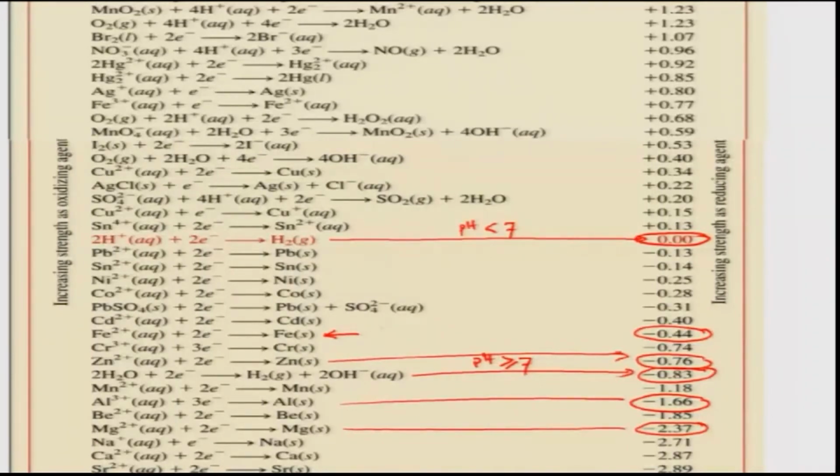In order to stop or minimize these reactions, we have to have a counter anodic reaction, which will supply electrons for these reactions. So, iron dissolution will be minimized, but of course, zinc dissolution would increase, and if we club iron and magnesium, magnesium dissolution would increase. That is why magnesium and zinc are used as sacrificial anodes for protecting iron objects.